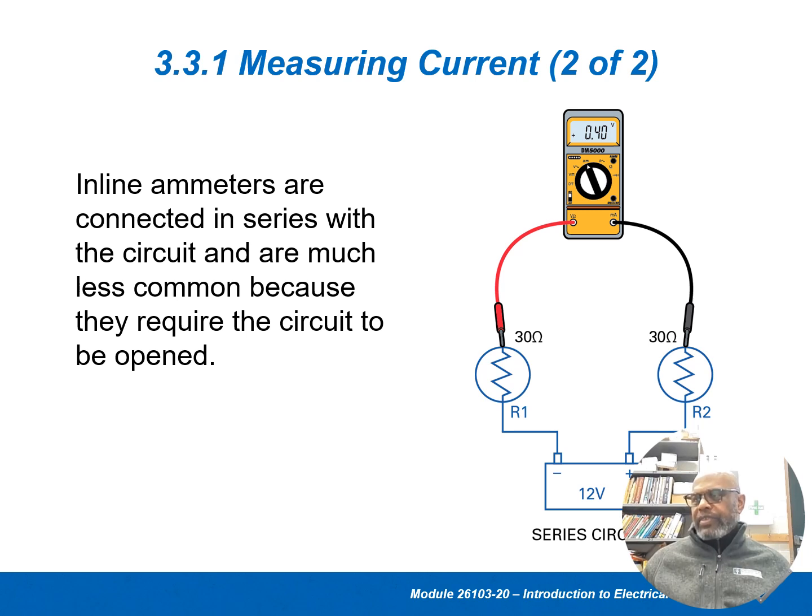Again, why it's not safe is because you can see this probe is touching one side, current's going through it, going to the other side, and the thing will actually run. But the problem is, again, the safe handling of electricity. So it'd be a lot easier to leave everything connected and use a clamp-on amp meter to do it for you.